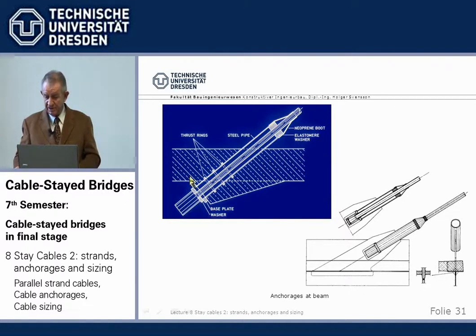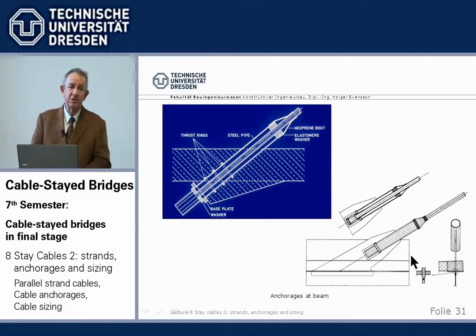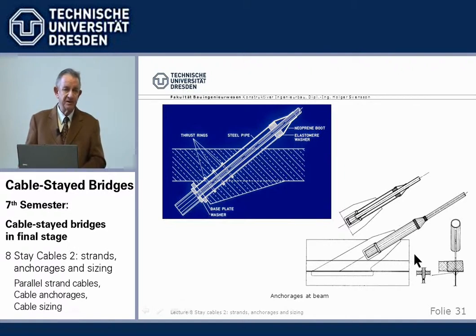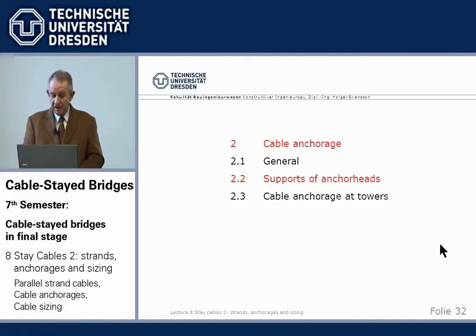What you do is you make a pocket: you cut a slot into the top flange here, like this, stick the new plate through, and then make a butt weld here. And this butt weld has the same strength, fatigue strength and so on, as the rest. So that's a little detail, of course, you have to take into account.